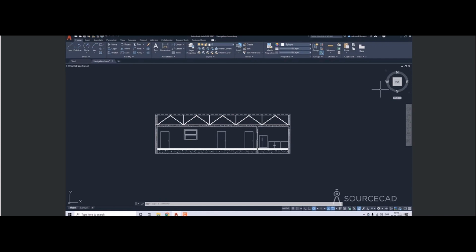If you want to know more about this view cube, check my AutoCAD 3D course. I've explained everything about View Cube and all the 3D tools there. Here, we'll only talk about these two arrows. So using these two arrows, you can move your view by 90 degrees.